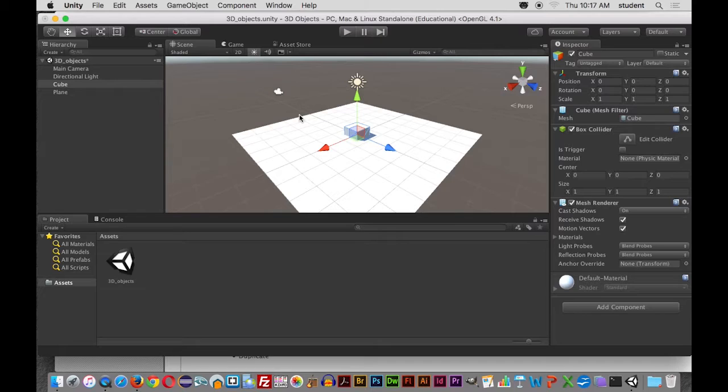So basically, if I change it to local on that object, and say this object is way off, somewhere out in space over there, and then I want to rotate my scene. Well, my scene won't rotate; it'll rotate on that object. So when I rotate my view and move it around, it'll rotate based on that X, Y, Z coordinate of that object. You see, by changing the local. So local is that 0, 0 mark.